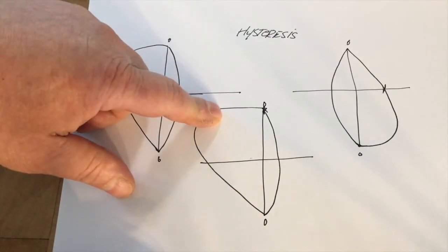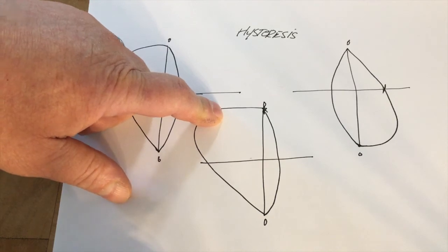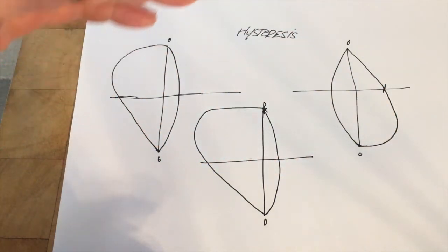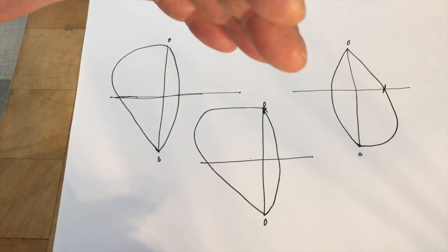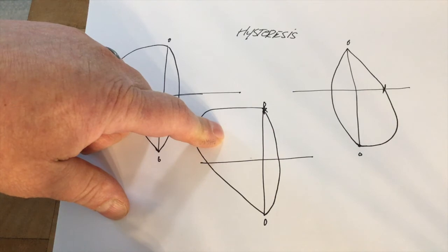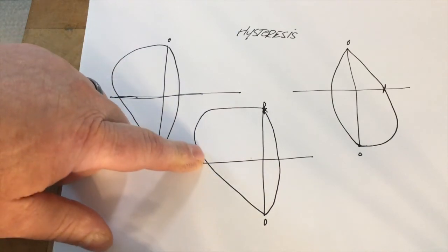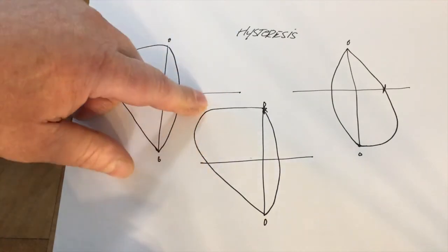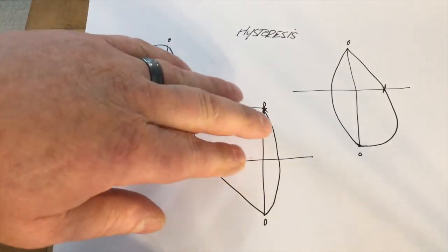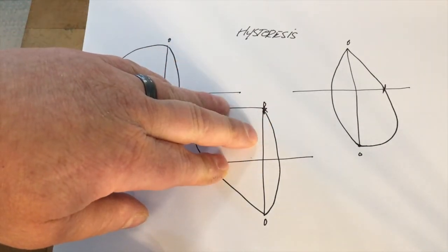I don't think this is as bad as on the compression side, because on the compression side you're going up the front side of the hill. But to tie the right front down and you want the ultimate compression with your right front, you don't want your tire locking when it goes over a bump, because then your traction will get tossed out of the right front.